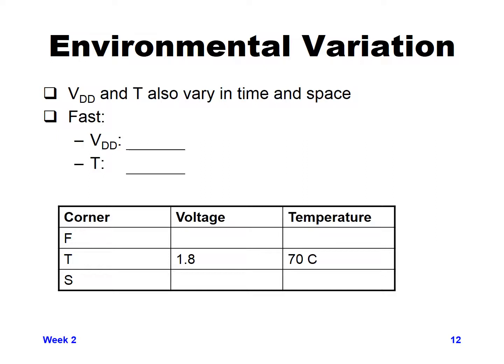In other words, as you supply your voltage to your IC chip, there could be areas where they're consuming a lot more current, and as they consume current, the voltage is going to dip in that area locally. And then in other areas, it's not dipped, and so you'll get some speed up or slow down of transistors based on that.